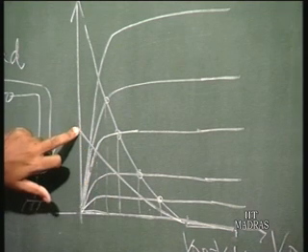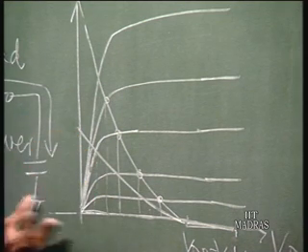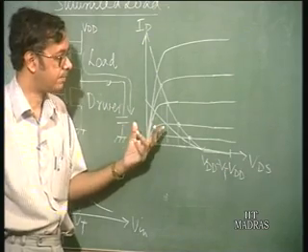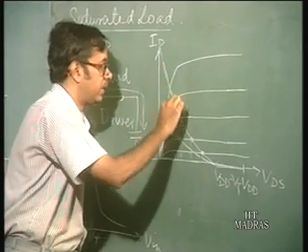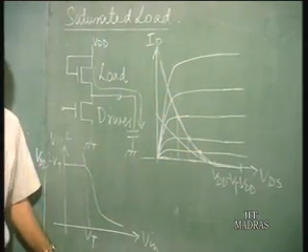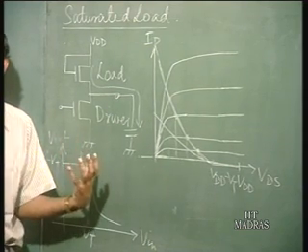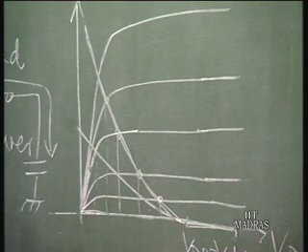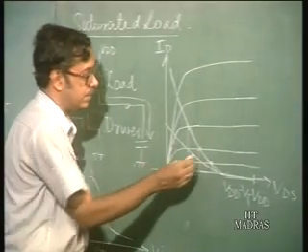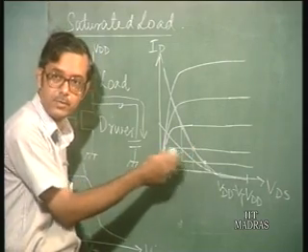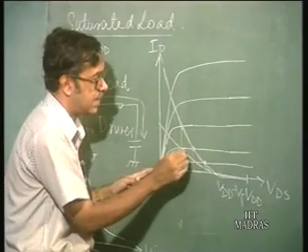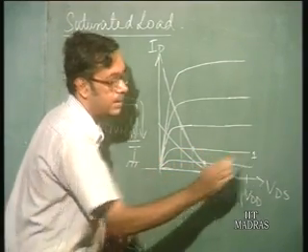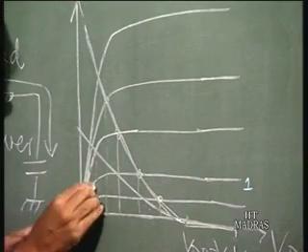So, the transconductance parameter is less. Now, again, suppose you consider that this is the load device, and for the driver you have a device with a larger transconductance. All the curves are going to move up for the same Vin. Say, for example, consider this curve 1, and another curve